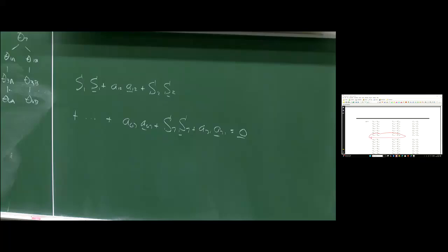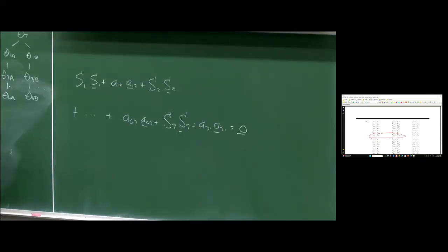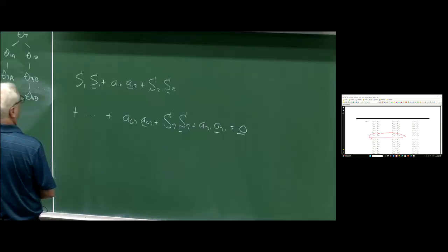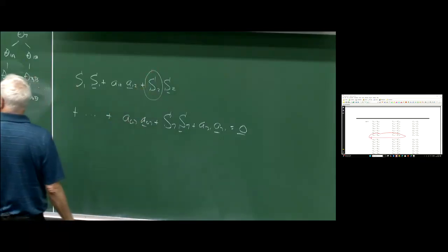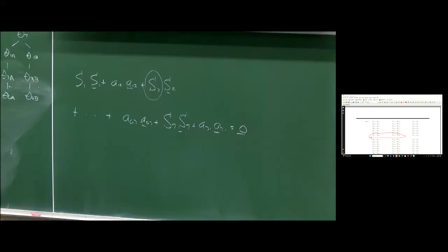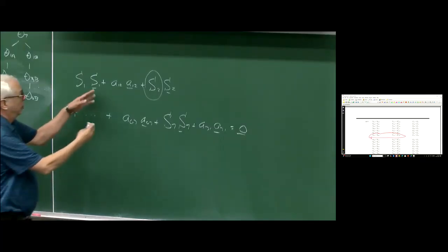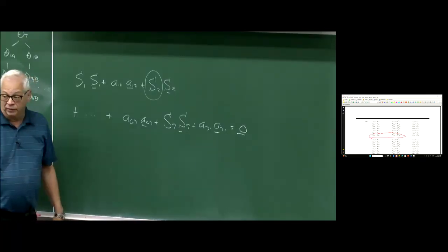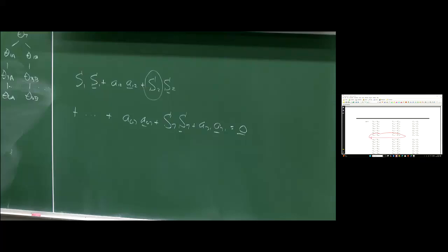And then to solve that, it turns out that there are three distances that we don't know. One of them was S2, and the other ones were in the dot, dot, dot. I didn't write them out. So to solve this, we have a couple of choices. I could evaluate all the vectors in a common coordinate system, and there are 14 of them given in the appendix. Because I know the joint angles, I'll get the three components of all of those vectors in that coordinate system for the A case and the B case, and I can solve three equations, three unknowns.